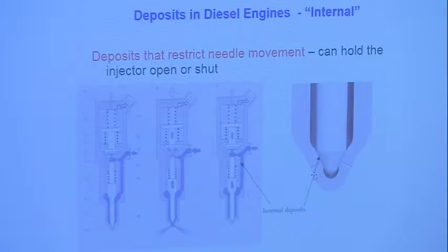And in terms of internal deposits, this is what I mean. For example, internal deposits could occur on surfaces like this, here, for example, or here. The arrow is not pointing in the right place. But anyway, it can make the needle stick and not move very freely.